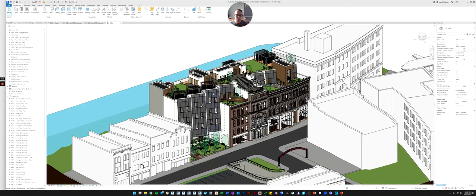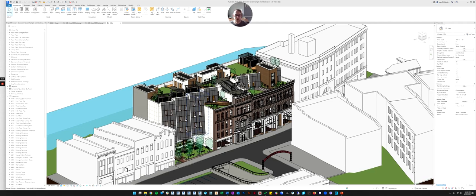If you remember from the Revit workflow discussion we had, we always model in Revit in 3D first, and then views are simply ways of slicing up the model. That's what a view is. In its most basic form, you just constrain the 3D model to only show what you want it to show.